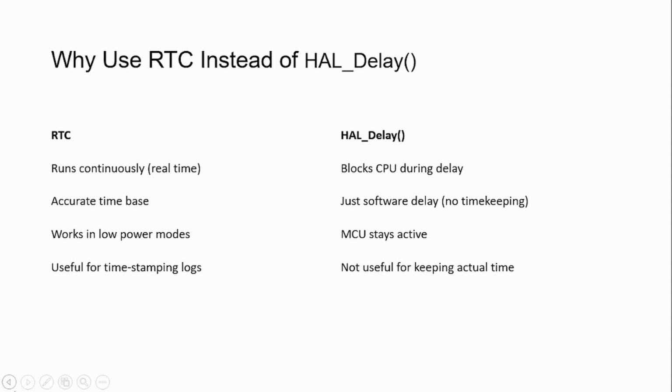Second is accurate time base. If you generate delay using HAL, you have to keep many things pre-calculated and use those things. But here in RTC, it is very accurate compared to this normal delay, right? It's not just a software delay; something different is there.